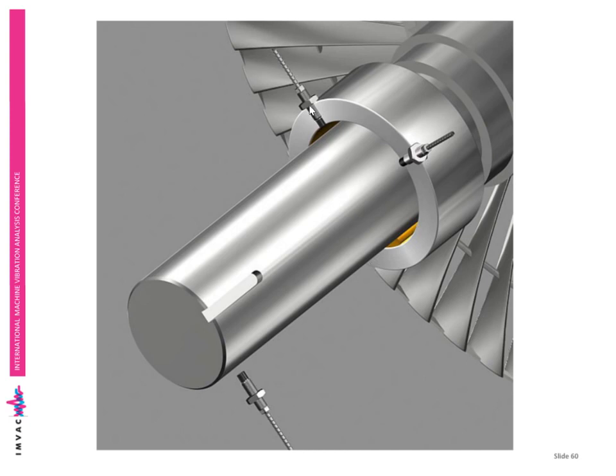Here, typically mounted near the bearing, they are watching how the shaft is moving. So we've got an idea of what's happening in the bearing, and we'll have these X and Y probes on each bearing, and then we might have just one keyphasor looking at this. Now, in reality, there might be multiple keyphasor probes for redundancy and so on, but that's another story.